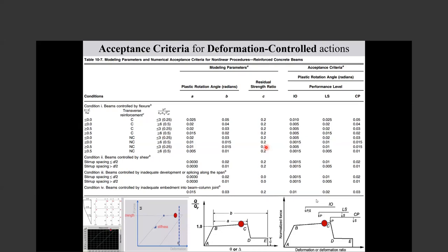And many times if you use those modeling, the same that you mentioned, beam column or soil, the performance of the building improves. Because when the connection to soil is very rigid, the damage usually concentrates. But if there is some flexibility, the damage will distribute among the load, and the possibility of getting the performance improved is much more.